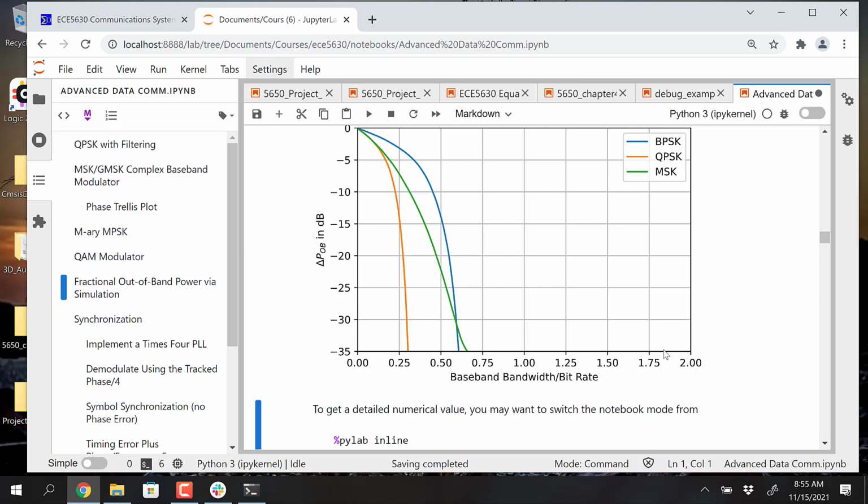that's not the end of the story, right? The thing you want to know about GMSK and MSK and BPSK and QPSK is they're constant envelope modulation schemes. There's no deviation of the envelope as long as there's no filtering. And even with filtering, there's a minimal amount. If there's filtering, envelope deviations get introduced, but pulse shaping with Nyquist pulse shapes, either the raised cosine effectively end-to-end, or square root raised cosine just for the transmitter. Now there's an issue that's referred to as peak to average power ratio issues because the signal does fluctuate, and that's now the norm in cellular communications.